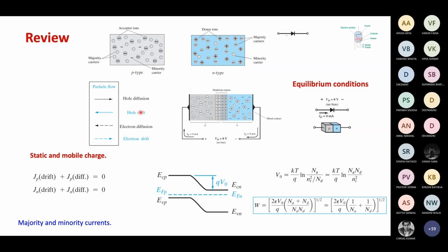And the reason for that is that even in the absence of any voltage, there is an electric field in the junction, and that electric field can sweep the minority carriers across the junction. If we apply a voltage, this electric field will change, but it does not change the current value significantly, because current depends on electric field and mobility, on the velocity of carriers. And when we join them together, it's almost this product of